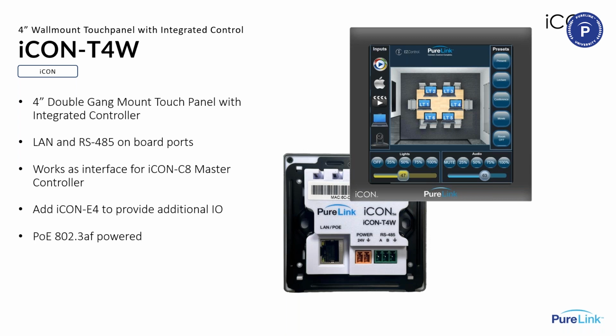Okay, so we'll start with the 4-inch touch panel. This is the iCON T4W. It's a double gang wall mount. It's powered off of the lowest PoE power standard, which is 802.3 AF. That's a 15-watt power standard. We don't actually even use all of that. So these all run very cool to the touch. There's no fans or anything of that nature.